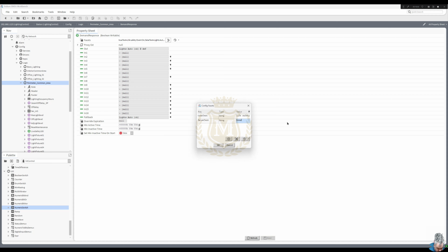if a demand response is received, the maximum light level output will be reduced. Yeah, over. During schedule occupancy and proof occupancy, light output will be adjusted. Okay, so that's not going to be a set one. We're actually going to have to adjust that. So let's put that to light occupied level.